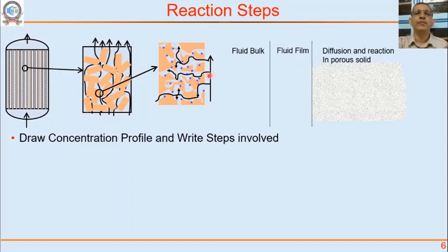So if you think about, let's say these active sites are silver clusters in ethylene oxide manufacture, you have ethylene and oxygen going, ethylene and oxygen gas molecules diffuse inside, they go towards this, let's say, active site silver center where reaction occurs, ethylene oxide is formed, ethylene oxide diffuses back out and then goes along with the gas. So this is how actually reactions happen, and the porous nature of the catalyst provides large surface area on which these active sites could be deposited.